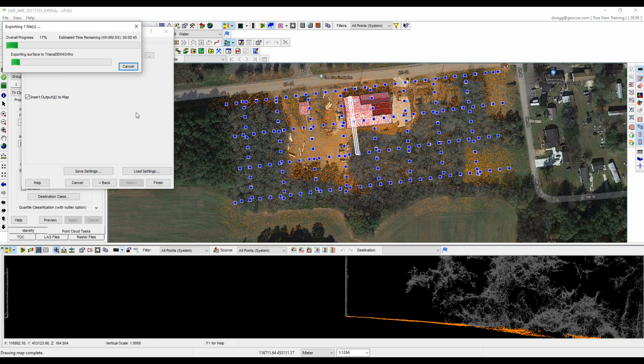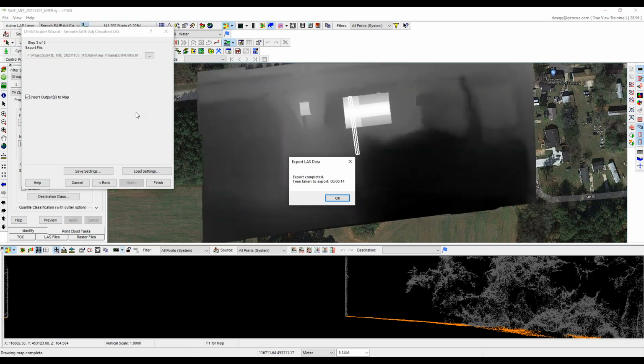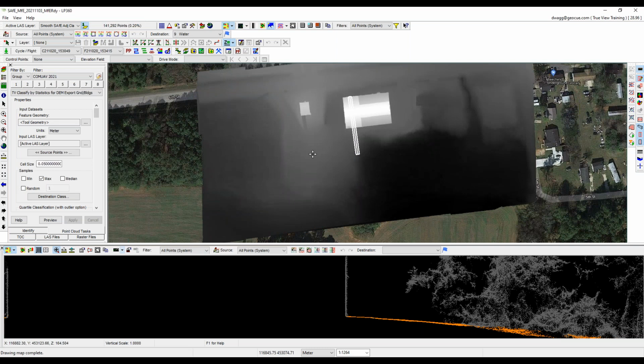So when we go to do the processing with Metashape for EVO, we want to have a digital elevation model, because if we have Metashape create the model, it takes a while for it to create a point cloud off of the imagery and then make use of that. And you don't have any control over that. Whereas here we get to generate the elevation model pretty quickly off of our LiDAR data.